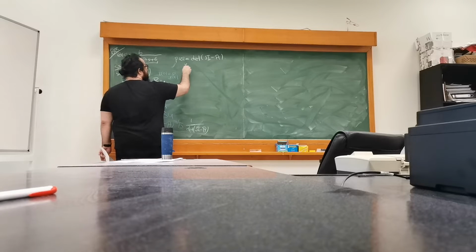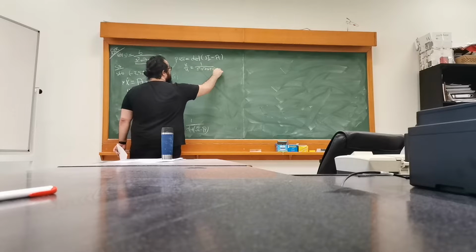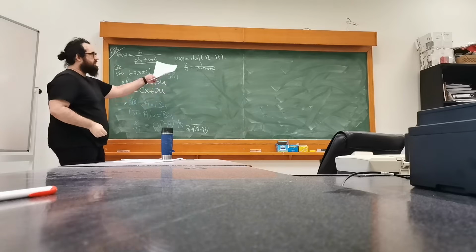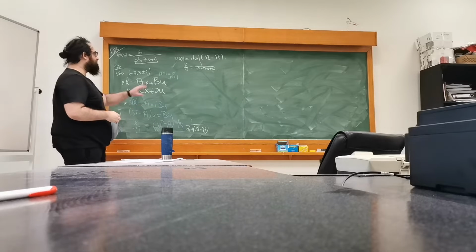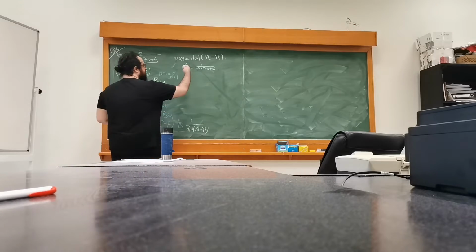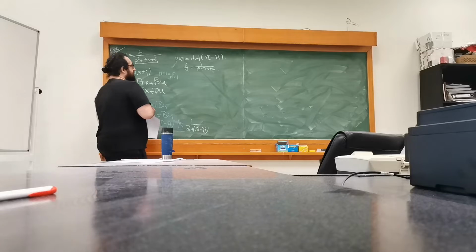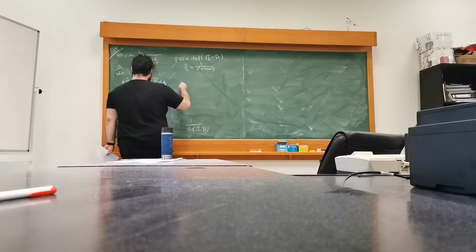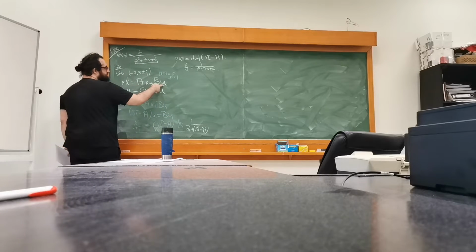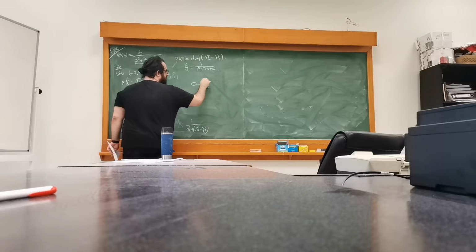So I'm basically assuming that this should be s squared plus 7s plus 6. Why? Because I want to determine what A is, and it's only relating to the denominator, so therefore I'm using this relation here. And then I can work out what the actual output relation is, because since I have x dot equals Ax plus Bu, if I have x dot here, I'll have an integrator.